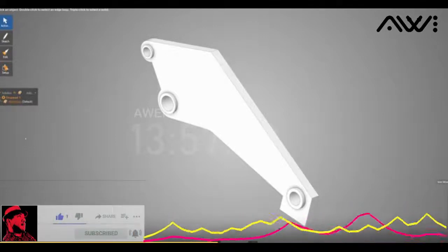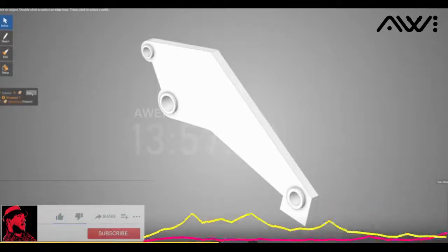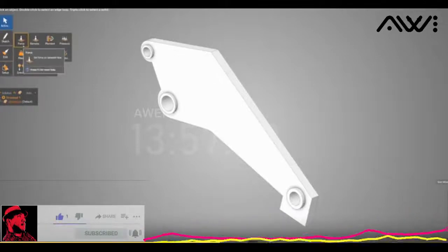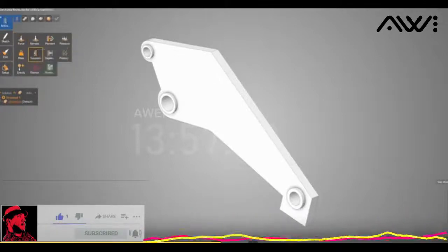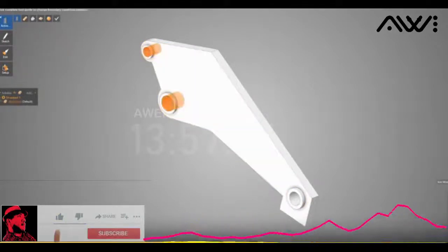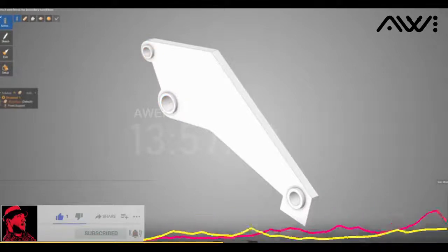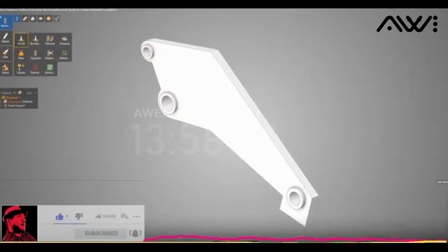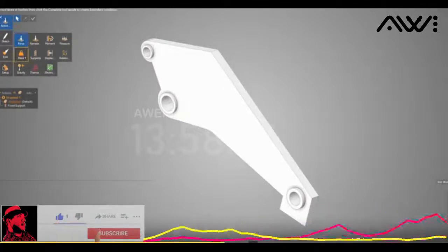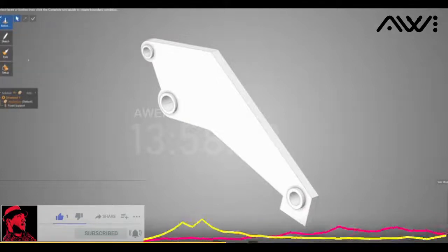So once we have our structural, we can go through and set up forces. So let's say under setup, very easy here. Let's do a support, fixed support here. If I hold down control, like any other traditional CAD package, these are my 2 fixed supports. Fantastic. Where's my force going to come from? Under setup, force. You guys can see this is not rocket science, right? We have the forces, we have the mass, we have the supports, we have the moments, pressure, everything you can do right here off the bat.